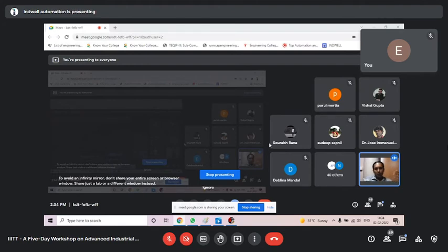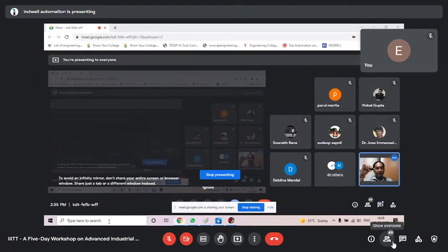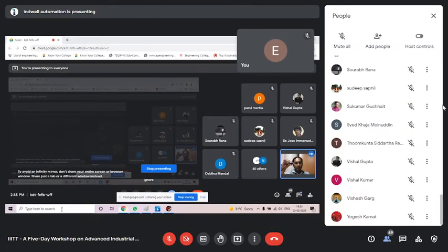On a computer also we have many USB ports. When you connect this USB to any USB port, we need to check to which COM port it has been connected, because each USB port will have its own address. That address we need to know. Where can we check that USB address? In Device Manager.